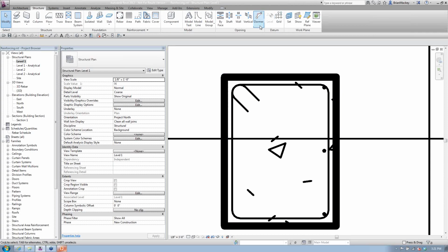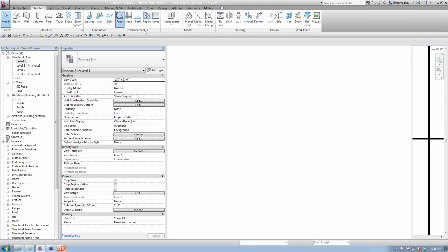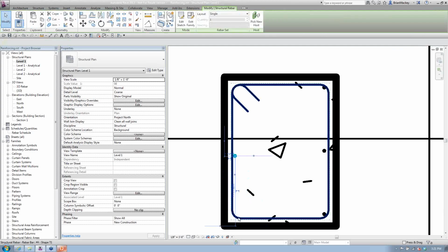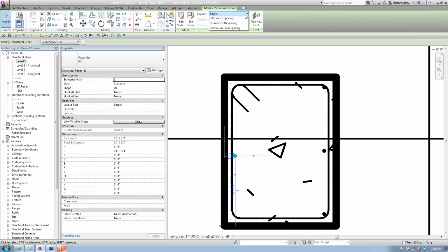When placing that individual rebar component, one of the things I like to tell people is if I wanted 3 going horizontal or 3 going vertical, a lot of times I'll just place it randomly over here where it needs to be, and then I'll go back and change it as opposed to trying to place it into the corner. Because if I change it now to be that fixed number of 3, these are going to be butting up next to it on the left side. So I kind of place it next to the rebar cover I want, and then it'll go through and do that.